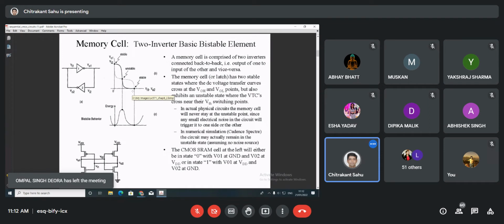And if you note in terms of energy, in the case of a CMOS also, we have seen that the power dissipation is maximum at this particular center when all the transistors are working, or you can say short circuit power dissipation when both NMOS and PMOS are on.